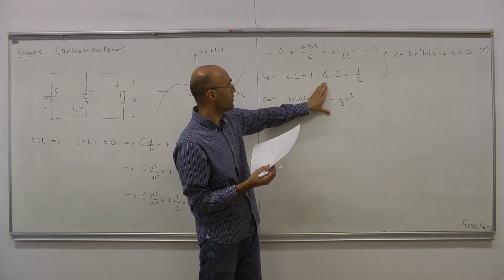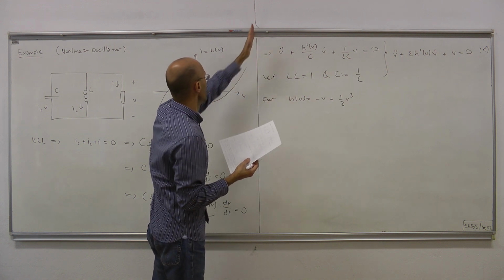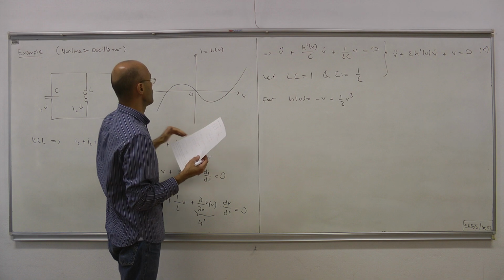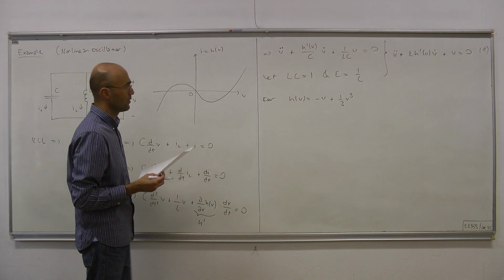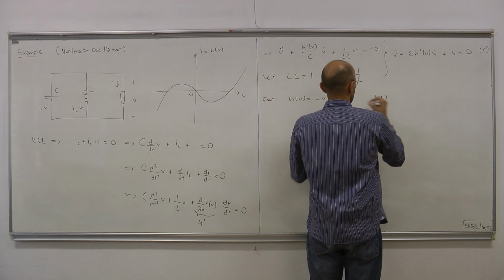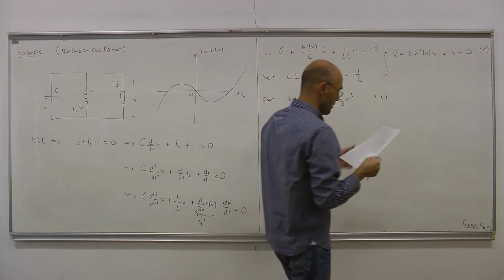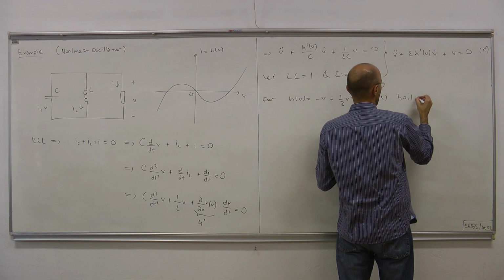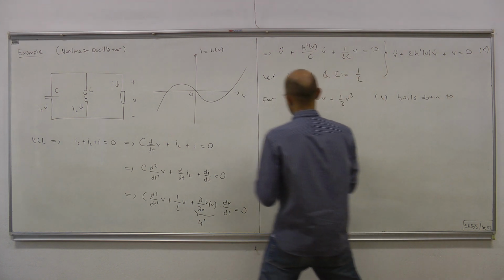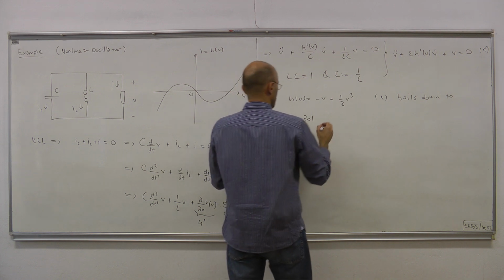So we can forget about the linear term for large voltages, and what we have is that polynomial increase in the first and third quadrants. So for such H, the general equation that we obtained, equation 1, boils down to this, the famous van der Pol equation.